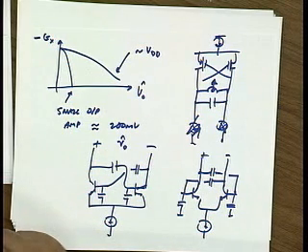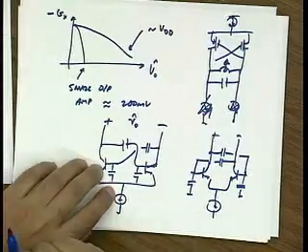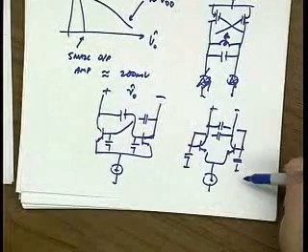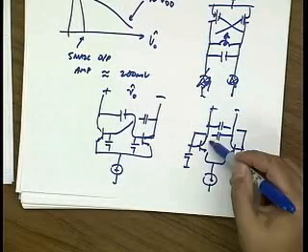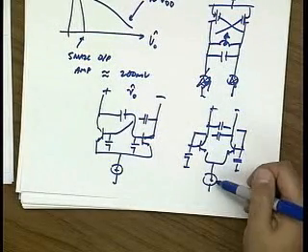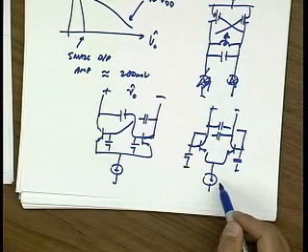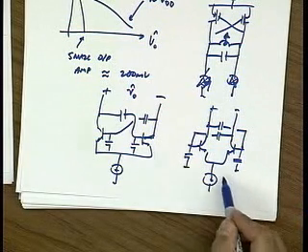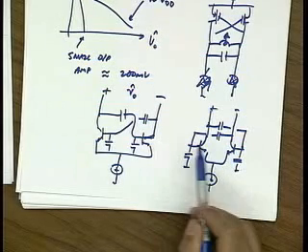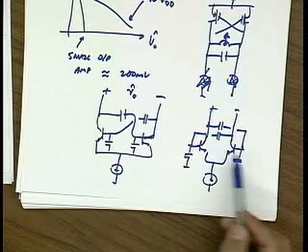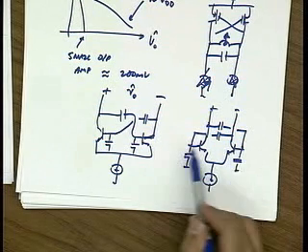Okay. Now, actually something interesting to make you guys think a little bit. You know, we're calling this thing an oscillator, but boy, it also looks like a mixer, right? I have a diff pair here. I have a current source. I can think of this current source as a noisy current source. That means it has RF current. And this is a switching pair, right? And there's an LO signal. What's the LO signal? Well, it's driving itself. So it's a self-oscillating mixer.